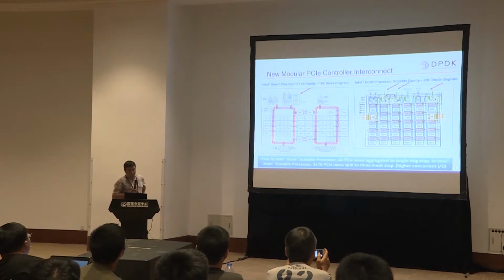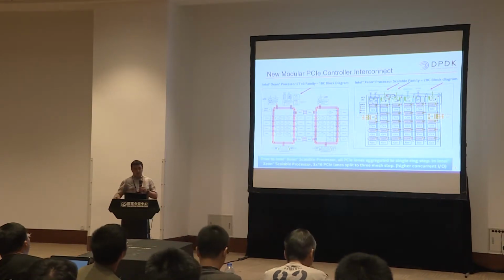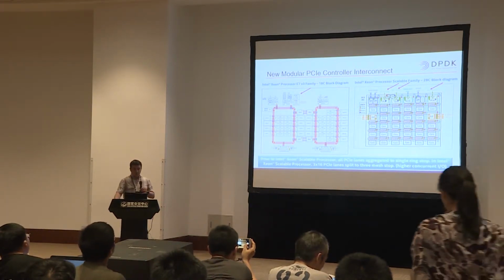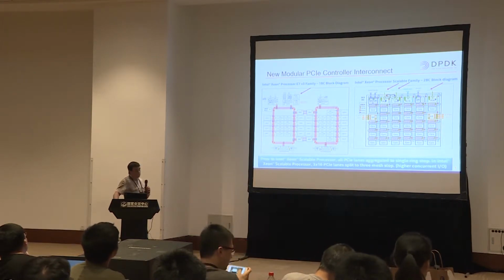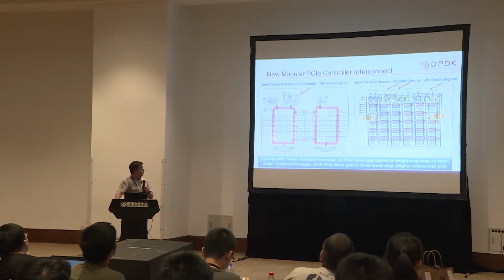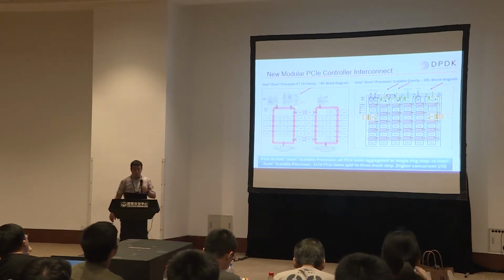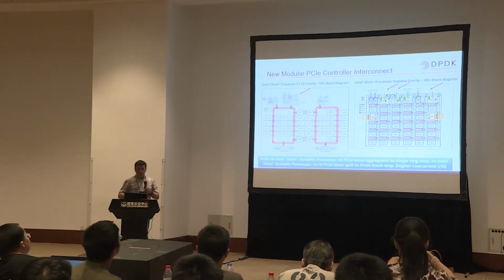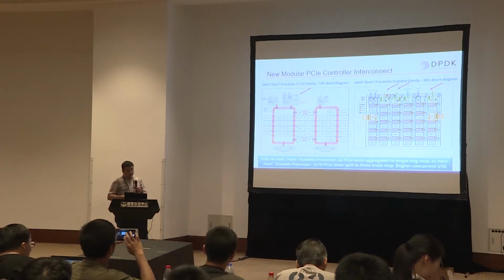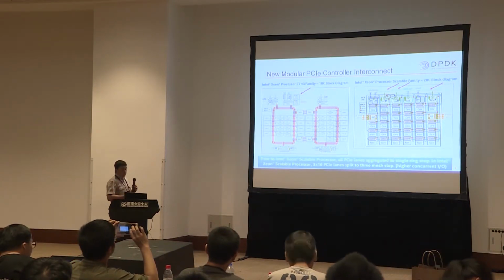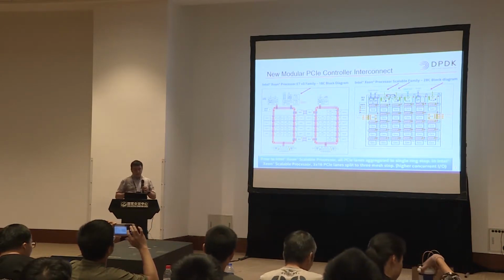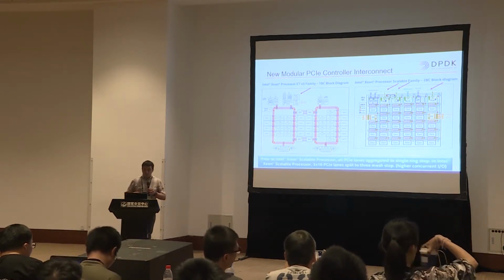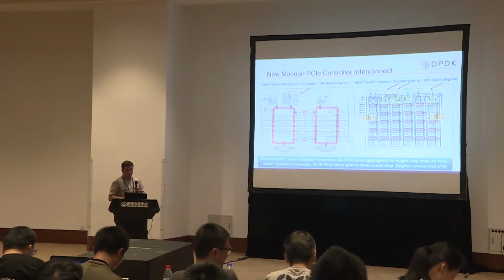Okay, so this is a high-level overview of architectural changes at platform level, comparing the latest Xeon server, known as Skylake, with the previous generation of Intel server platforms. The description of each platform component and its hardware optimization flow is definitely out of scope of this talk, so I will focus on those which are critical for I/O performance. One of the key changes is replacement of the ring architecture with the new mesh architecture, which significantly improves packet throughput and latency for time-sensitive applications and VNFs, which require large reads and writes between specific cores. Another noticeable change relates to the integrated PCIe subsystem.